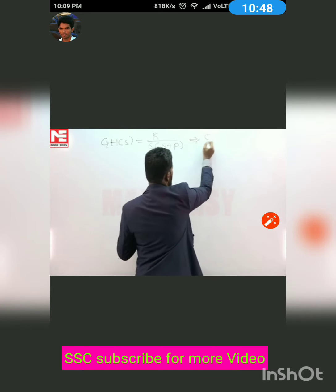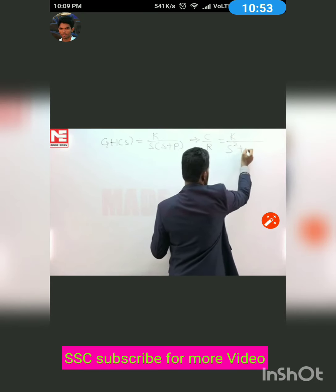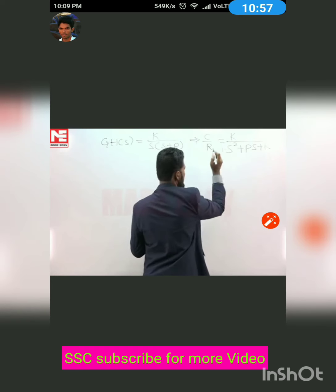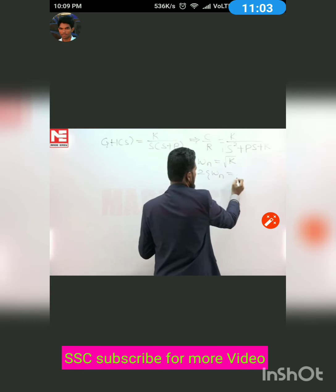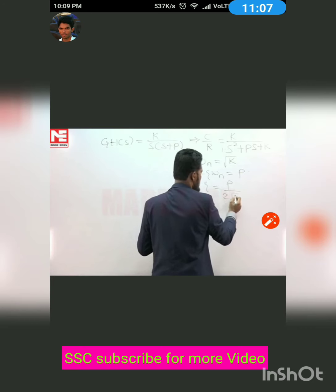From this we can obtain the closed loop transfer function to be K upon S square plus PS plus K. Since S square coefficient is 1, omega n of the system is root K. 2 zeta omega n of the system is P. Zeta is P by 2 root K.